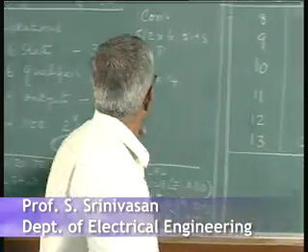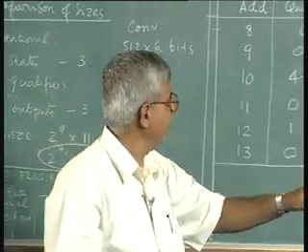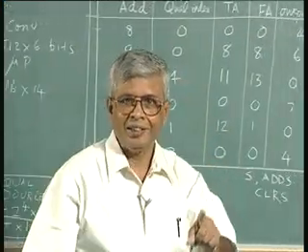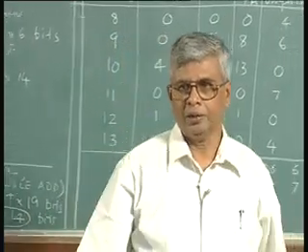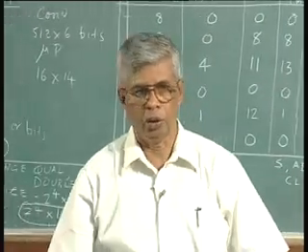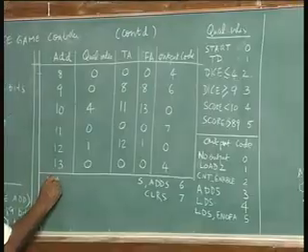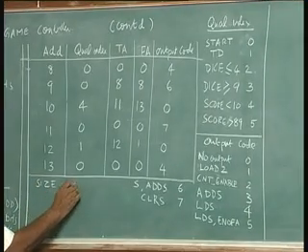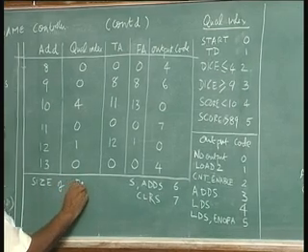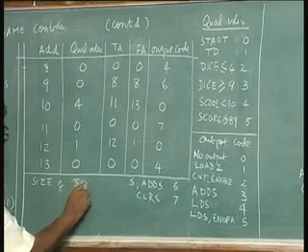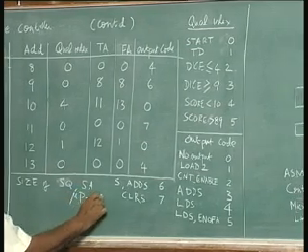You do the table: present address, qualifier index, true or false bit, true bit to be 0 or 1, the jump address, the next address, the output code. I can only give you the size comparison, the size of double address, single qualifier, single address microprogram ROM.